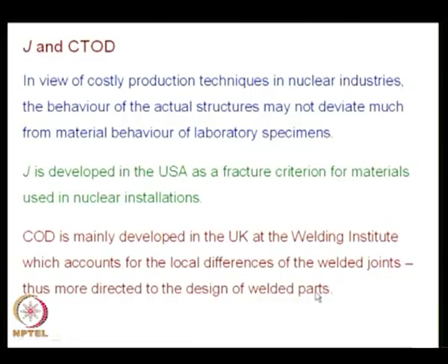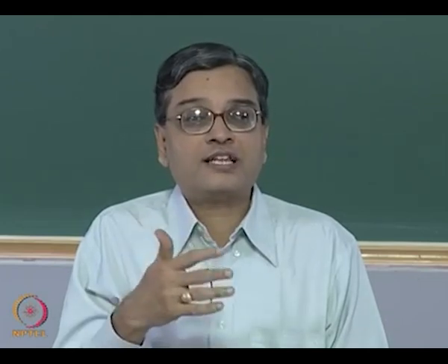See, if you look at welding as a manufacturing process, it has matured now, but in the initial stages people were not really understanding the variations introduced because of the welding process, because you need to have proper heat dissipation so that residual stresses are not built up after welding is done. So, people had to learn by costly accidents, and failures have been there. So, there could be local variations because of welding, that is reasonably accounted for in the COD design approach.